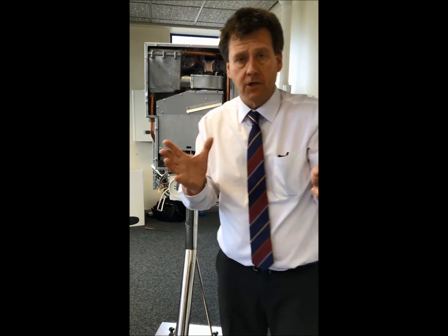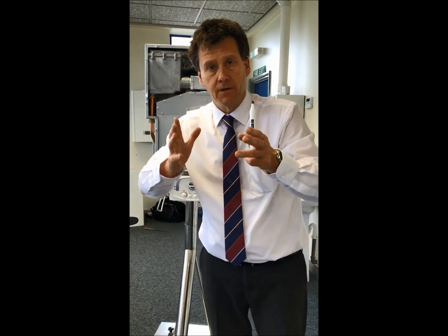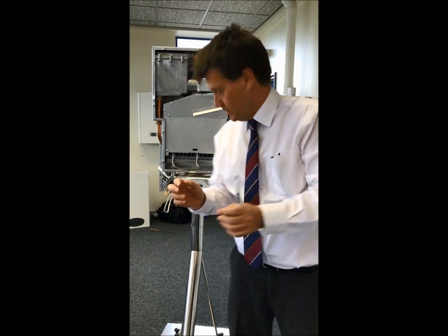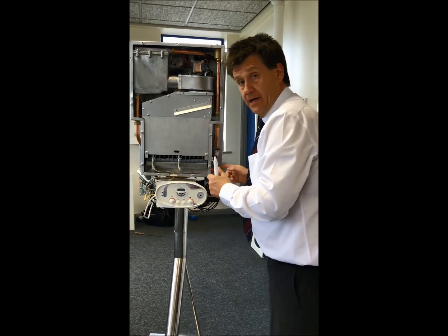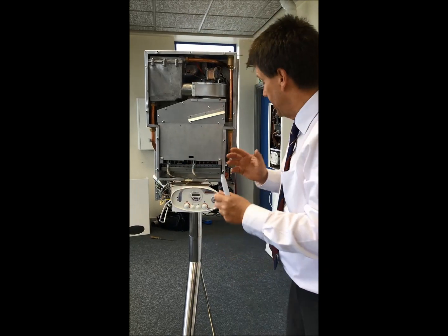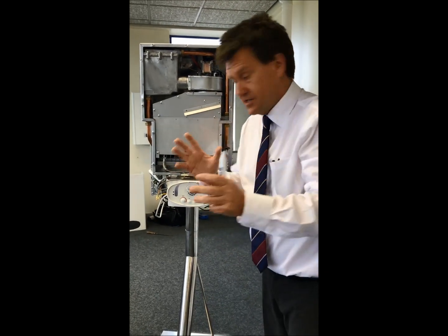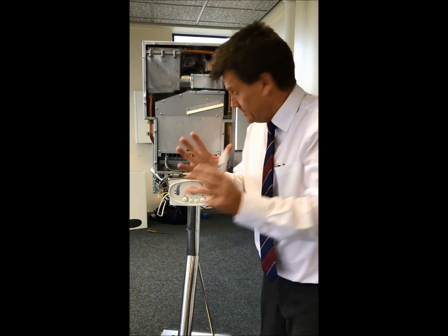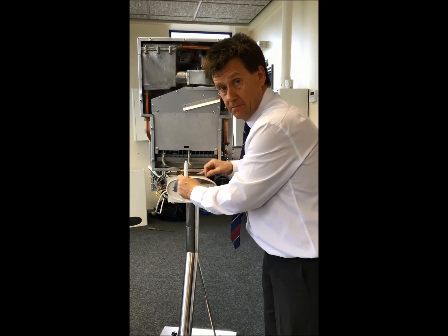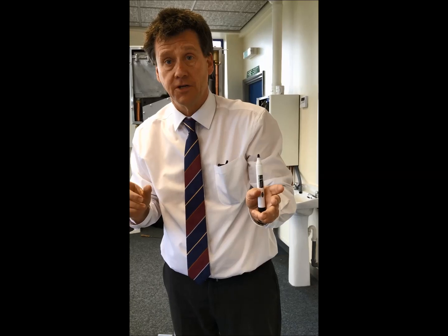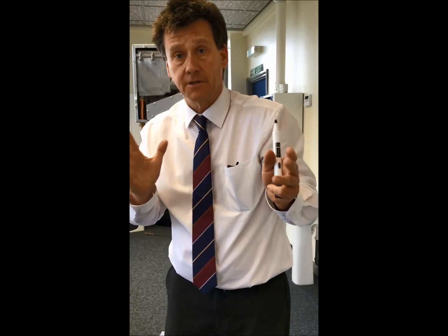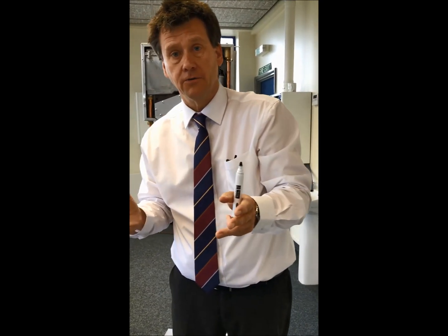Now, a regular component to be sold is a PCB, but what you must appreciate, with all manufacturers, PCBs are pretty much bulletproof. So the only time I will actually tell you there's a problem with the PCB is if there's no power to the pump, the first line in the sequence, okay? Now, the standard says, once the pump is energized, the circuit board behind the panel searches for the APS, the air pressure switch. This is very important, guys, because this is where you can actually buy a PCB unnecessarily.